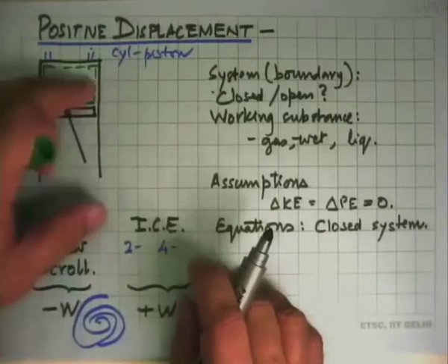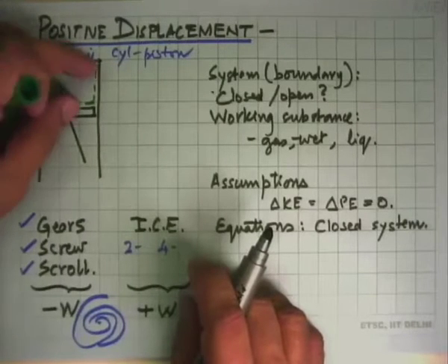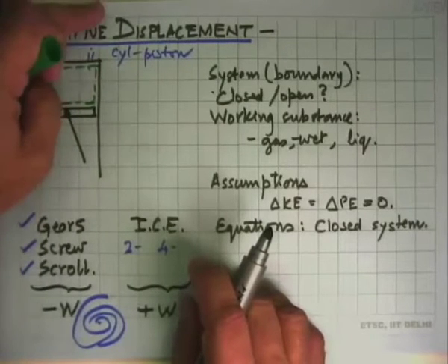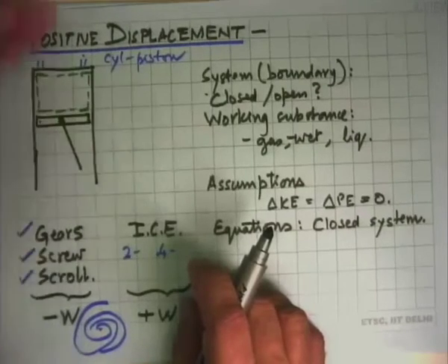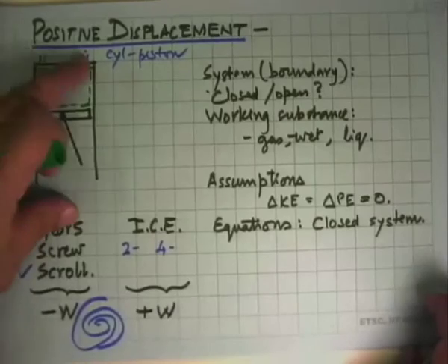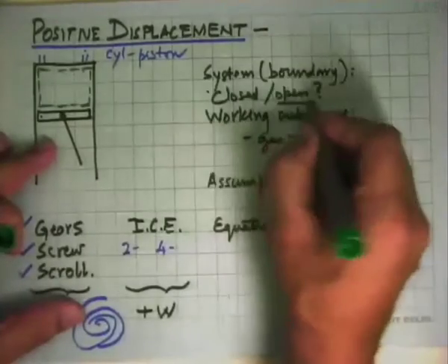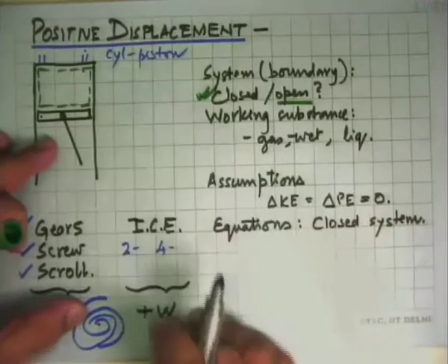And we know that as the piston goes up and down, the shape and size of this could change, and if there is an outlet, things could even be going out, or if there is an inlet, as it comes down, it could be taking material in. If these are open, this becomes an open system. Otherwise, largely we will look at closed systems.